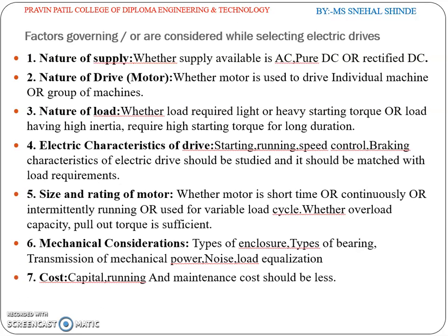Factors governing or considered while selecting electric drives. First, nature of supply, whether the supply available is AC, pure DC or rectified DC. Then nature of drive or motor, that is whether the motor is used to drive an individual machine or a group of machines.